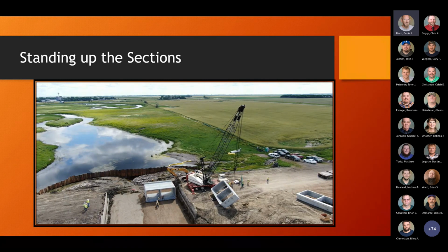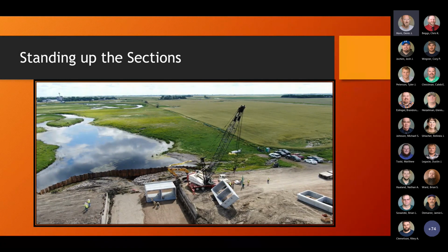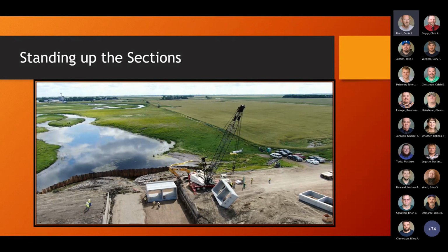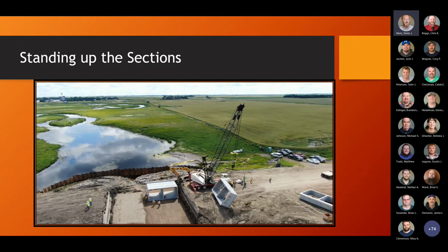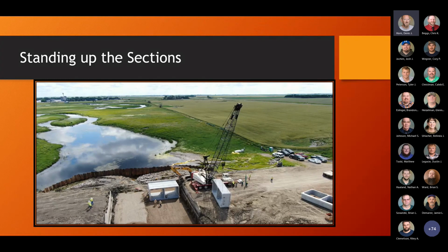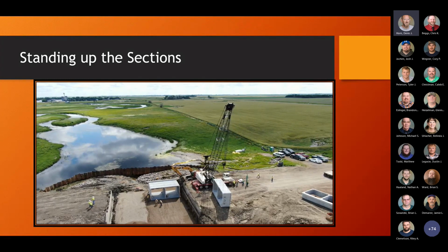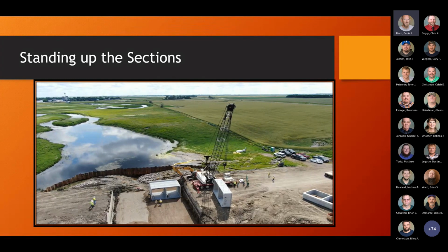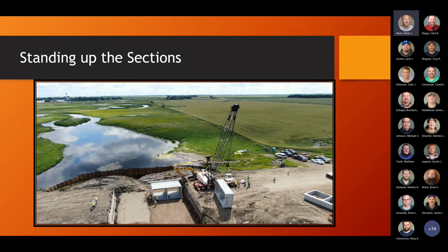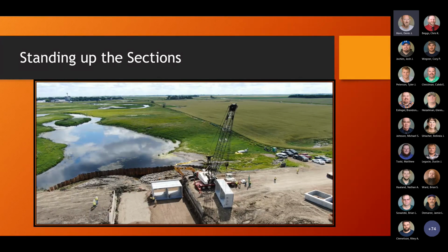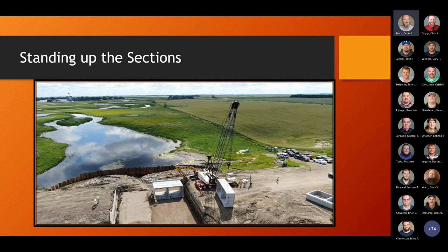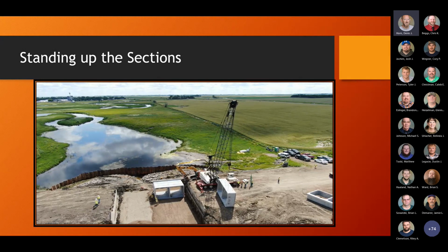The 5-foot wide sections were 51,375 pounds, and the 6-foot wide sections were 62,150 pounds. To stand the sections up, they set an old semi-tire on the ground to cushion the box when they pulled to stand up the section. The very first one they tried with 2 tires, and that left them leaning too much at rest. So they switched to 1 tire, and that was just right.